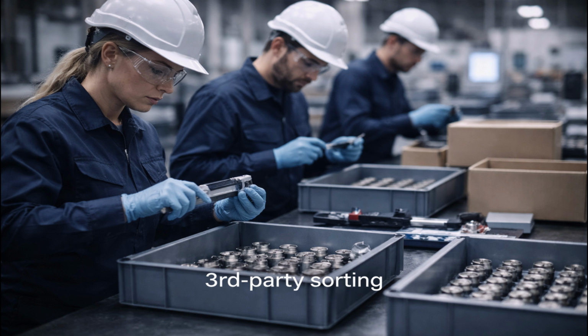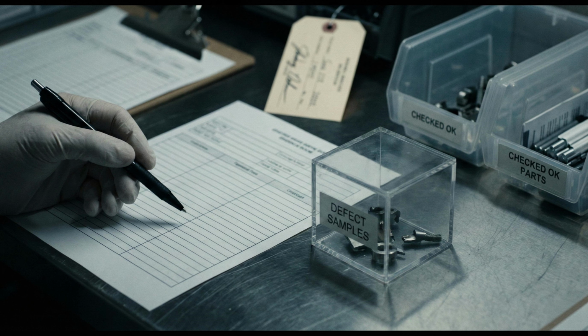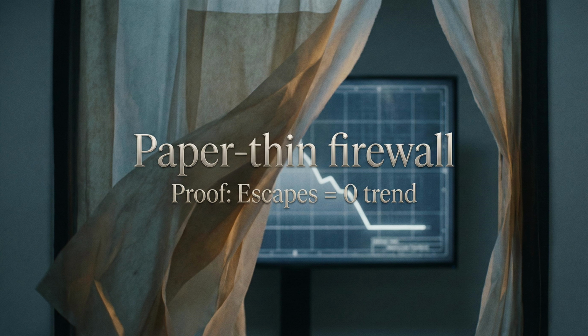But the lifeblood of D3 is this: proof that your added control works. "We inspected" is not enough. How many units did you check? How many defects did you find? Who did it and where? All signed and recorded. Stress test the firewall with a false negative challenge. Push a known bad part through the check. Does the system catch it? If not, your firewall is paper thin. Remember, in the OEM's eyes, D3 is often proven by a run chart trending to escapes equals 0.